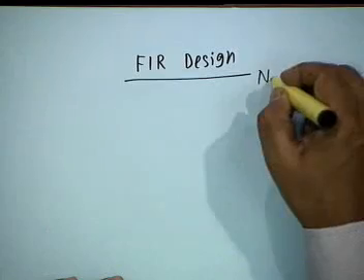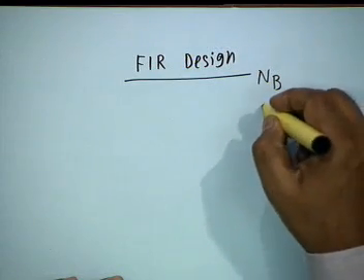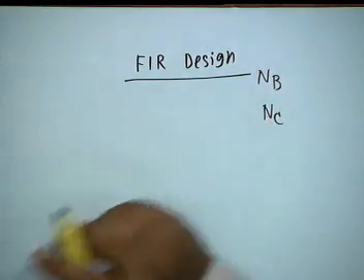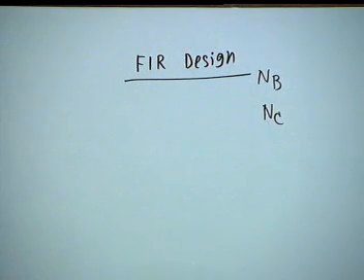You start almost blindly in FIR. In IIR there were analytical formulas for calculating the Butterworth order and Chebyshev order. There is nothing like this in FIR. In FIR you only have empirical formulas which may or may not work. If the empirical formula gives you an order of 17, you might have to use an order of 20 or 21. Empirical formulas always have this kind of tolerance, uncertainty.